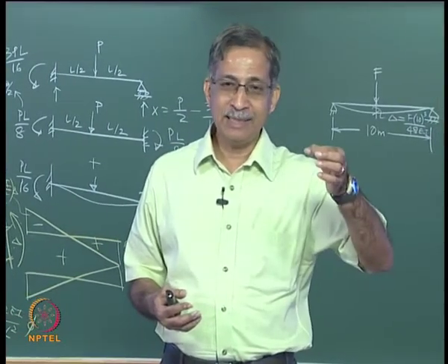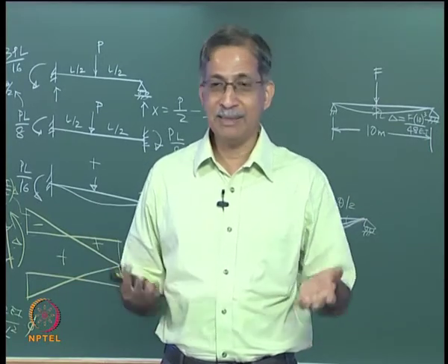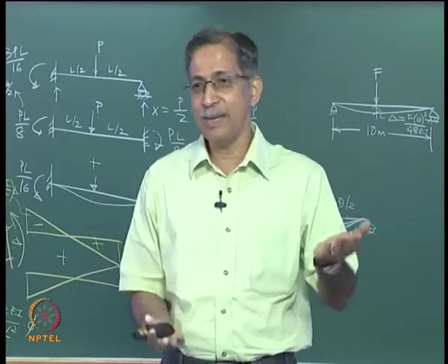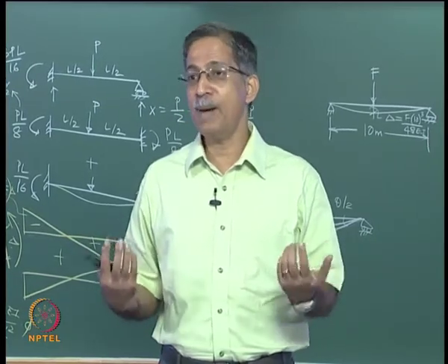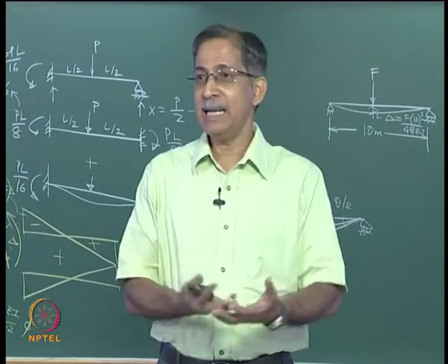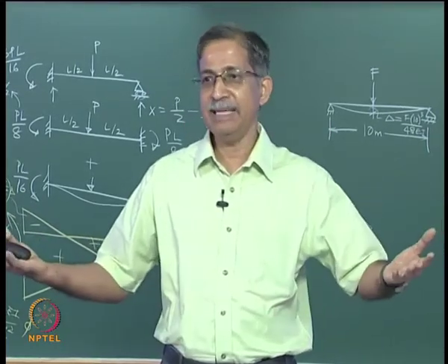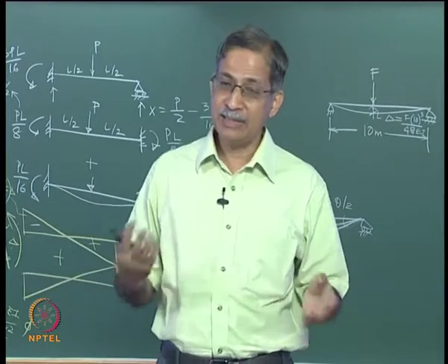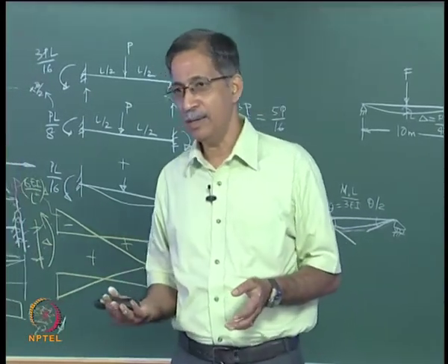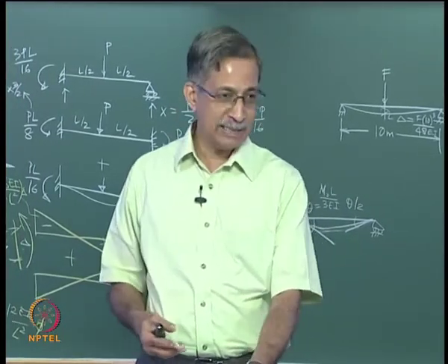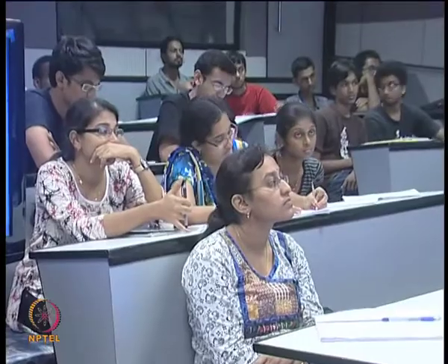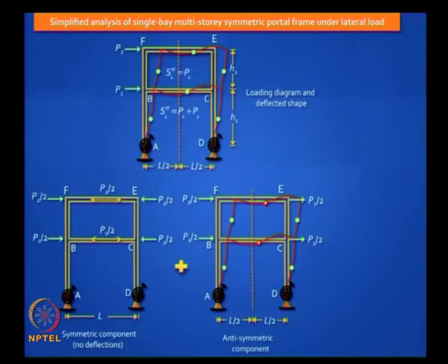Let us say you have an isolated footing but it is resting on very hard strata. There is no way the rock is going to rotate. Or you are on piles and the piles have a pile cap which is heavily interconnected. In such cases you can go for a fixity, but the spring model shows you can handle all conditions. Now, I am taking one type of frame only in this session.